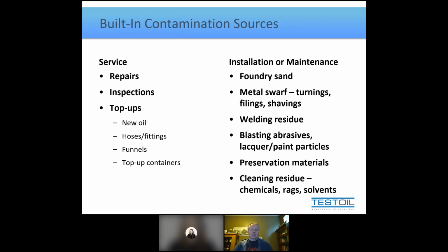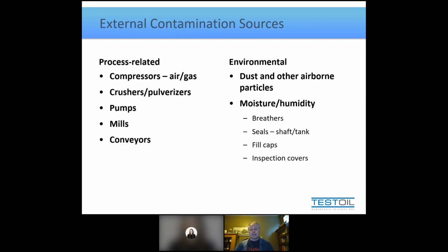The literally built in is pipe scale and corrosion of metal parts. Even from cutting new threads or welding material together, you can create all sorts of particulate on the inside as you construct or install and otherwise commission a brand new piece of equipment. So generally, these type of particulate, we know that we can remove them safely quite ahead of time by flushing. And we're going to talk more about flushing in a bit.